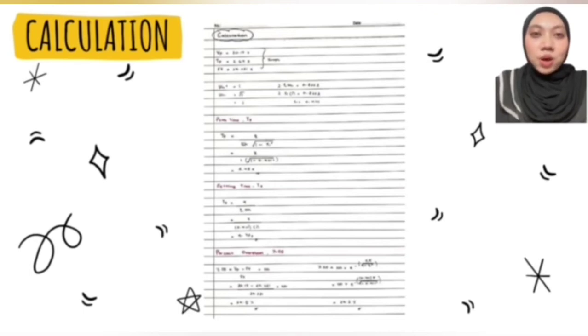Based on the graph, we obtain the peak value, peak time and final value for this calculation. I then use the formula provided to calculate the zeta and obtain 0.4111. I use the formula to calculate the peak time, which was 3.45 seconds. The settling time is 9.73 seconds and the overshoot is 24%.